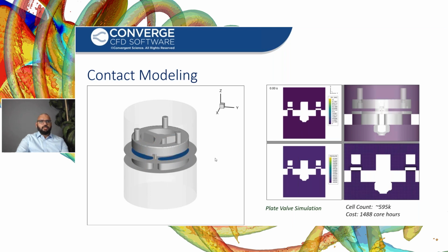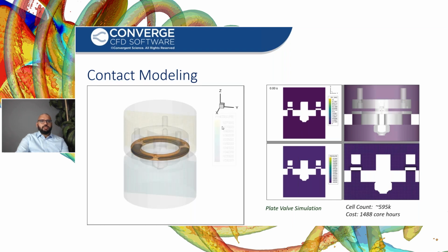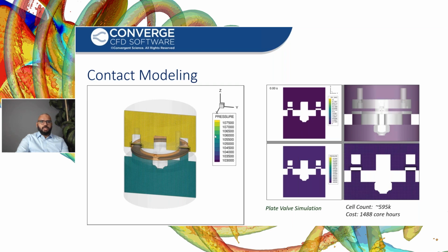As the piston compresses, the pressure rises up, which will cause the valve to rise up and the flow to go to the discharge region. Here you see a 2D slice view, which is also present on the right. This kind of shows you what we are seeing in the animation.